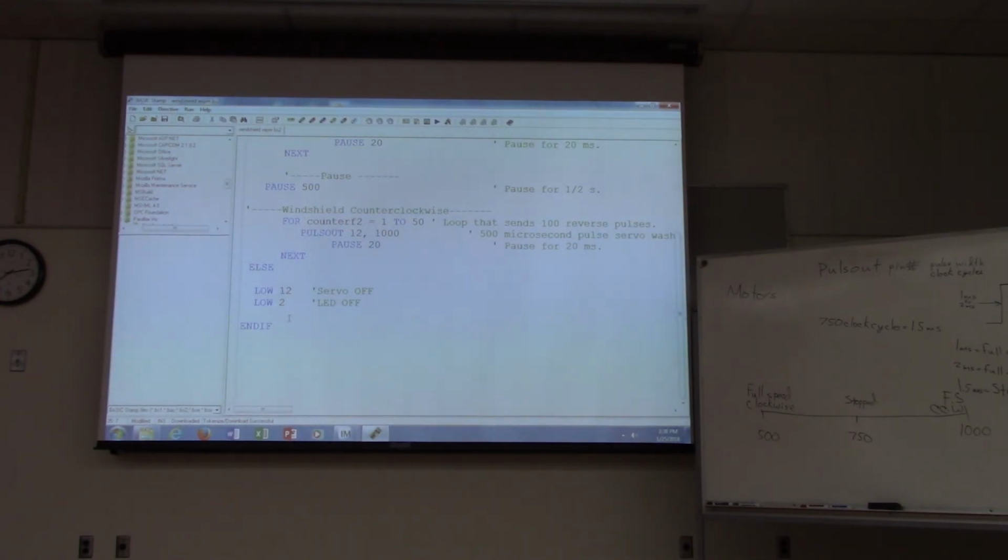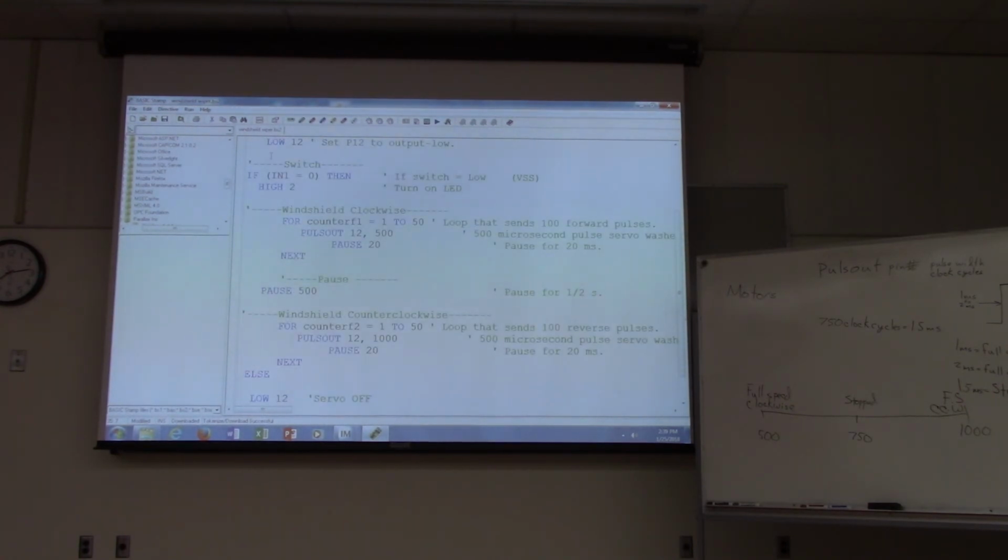Right, so if you don't have the wire attached, then you have basically an unknown condition. So that voltage at pin 1 might be high or it might be low. And so your program might behave in unexpected ways. It might do the high thing one time, and then the next time it might do the low part, because there's nothing connected to that pin 1.